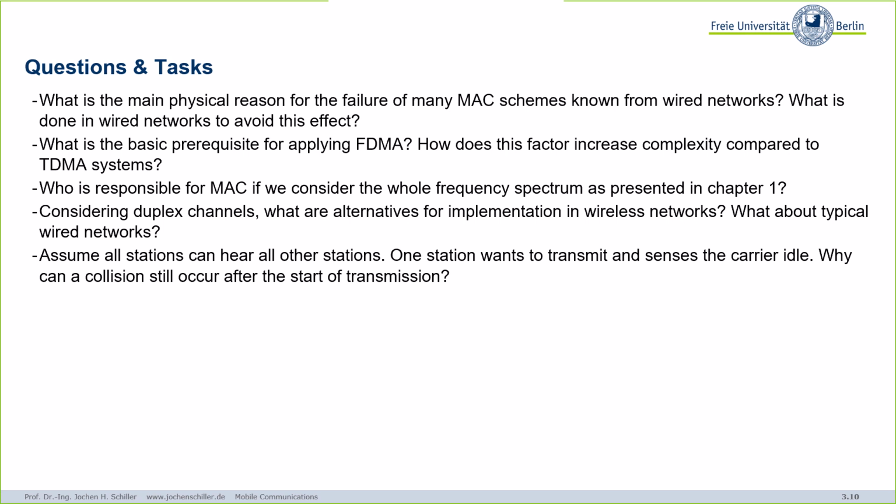If we start hopping, then you have to know the hopping patterns. You have to know the frequency, and you're right, we have to distinguish the signal from noise. So is this noise? Is this a signal? So before we can apply FDMA, we have to agree upon frequencies. For TDMA, it's not necessary. You simply listen to the medium and then something arrives. There's data. That's it.